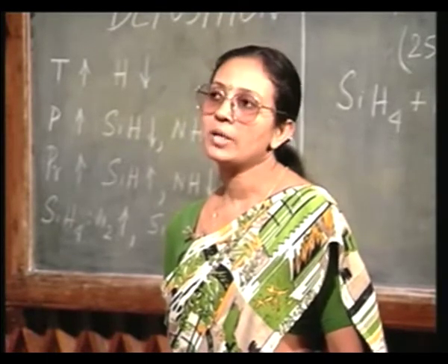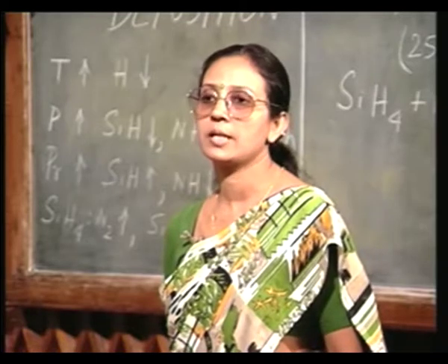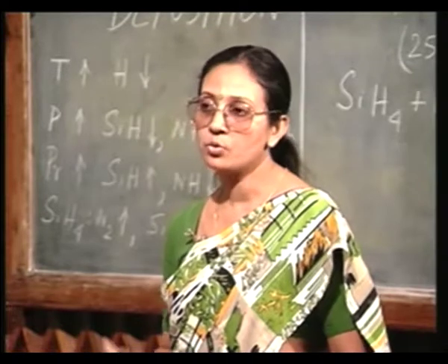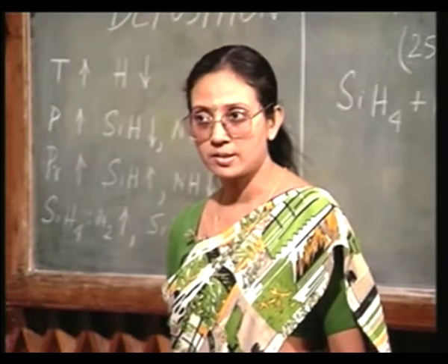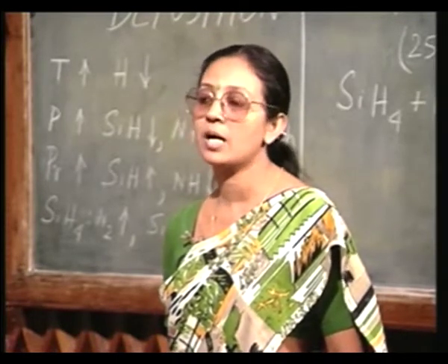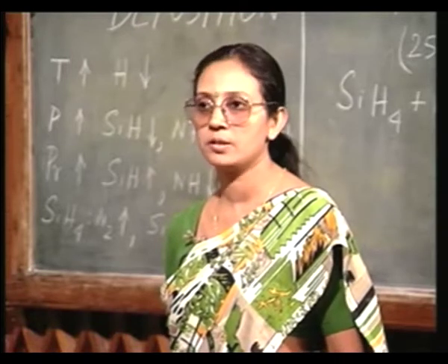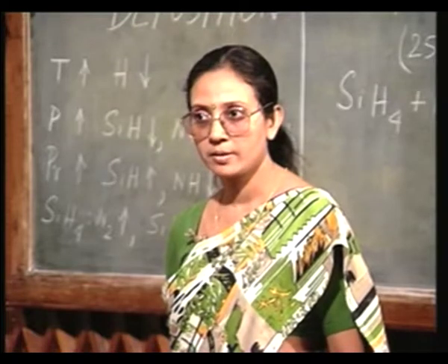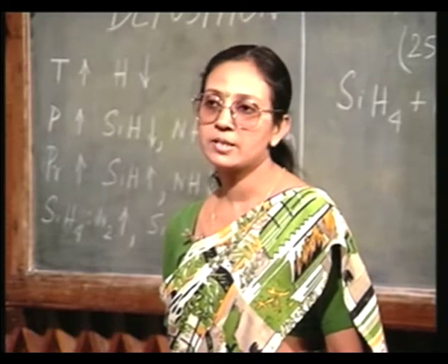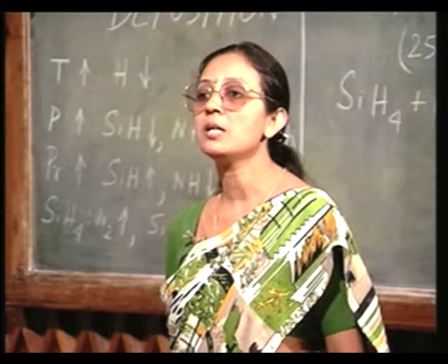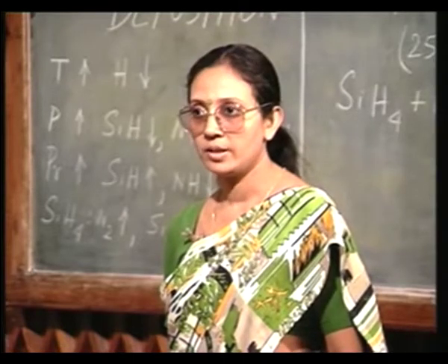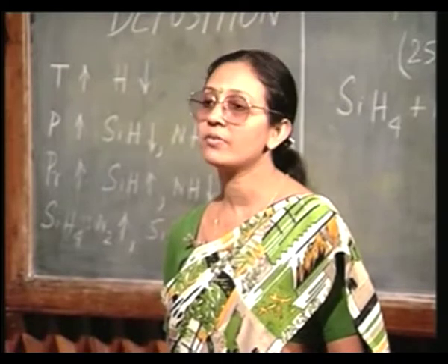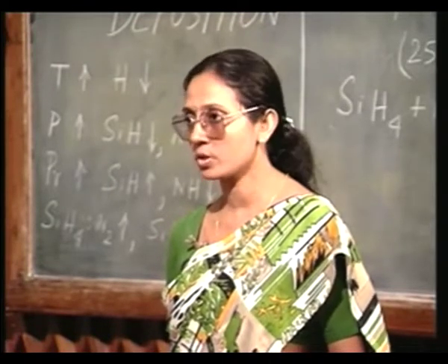Okay. So, we have various considerations, like we must have low contact resistance. So, how to keep the contact resistance down? What happens if you have a low doped region? Obviously, the contact resistance is going to go high. So, these are the various techniques we are going to discuss in the next class. Various constraints on metallization and various techniques to overcome those constraints.